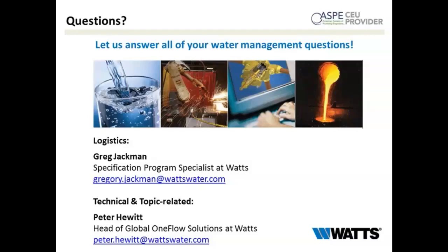Okay, thank you. Next question, does higher water hardness require more frequent changes of media? So again, just like other technologies, the idea is just through experience, we recommend a change out every 3 years. So depending upon the hardness, it's really not going to necessarily impact the life cycle of the TAC media on the inside. But again, it's always good to know what those feed requirements are via water quality testing. So again, that's pretty much the recommendation, we've stood by 3-year changeouts.